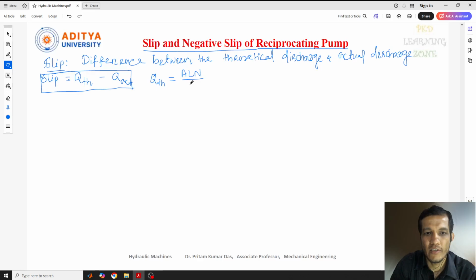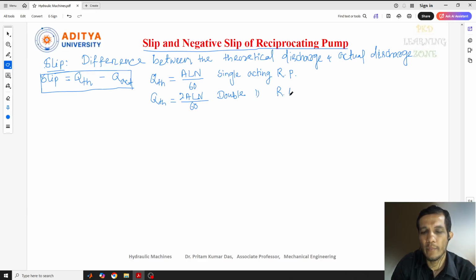For the single acting reciprocating pump, we got ALN by 60. And for the double acting reciprocating pump, we got 2ALN by 60. These two things we got in our last lecture, and there we can see how we got them.